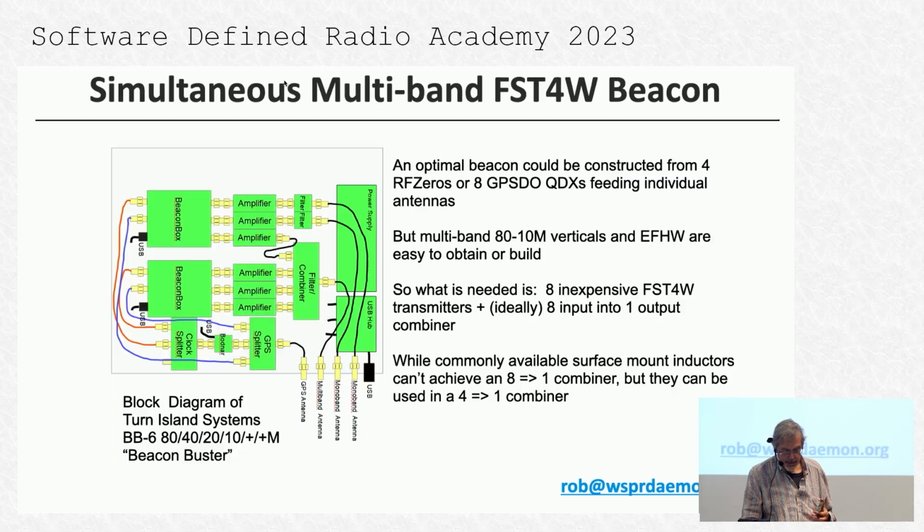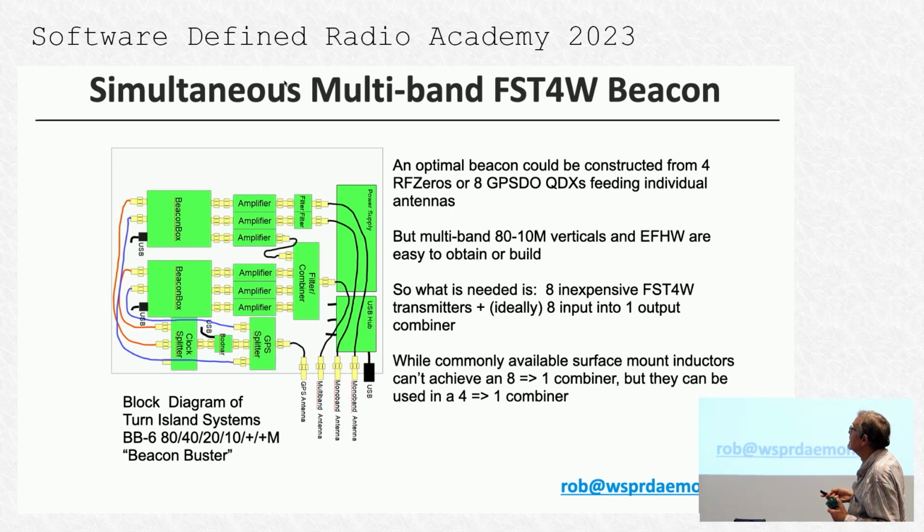So what Paul has done, who makes that adapter kit, he has designed a simultaneous multiband 4W beacon. This consists of an exciter, which is over here. The exciter uses the 5351s, one for each band, well, maybe one for each 2 bands, and then drives a little amplifier system that he's developed, which is about a 1 watt output device.